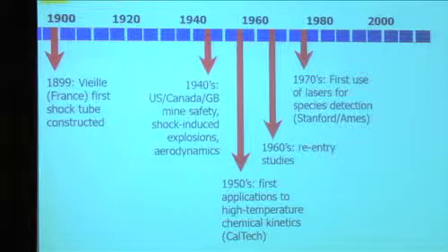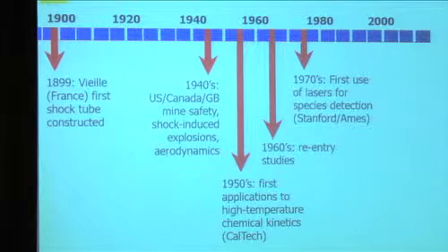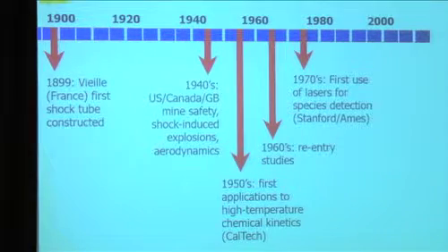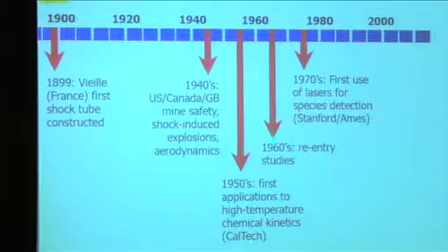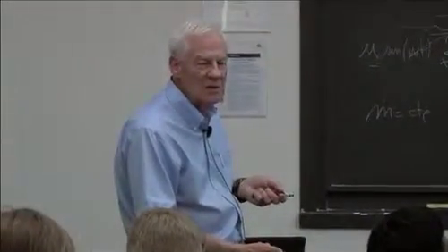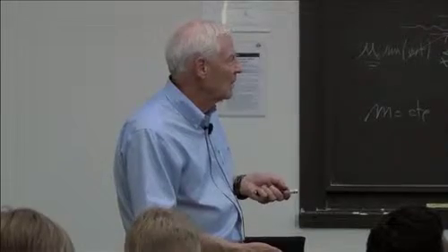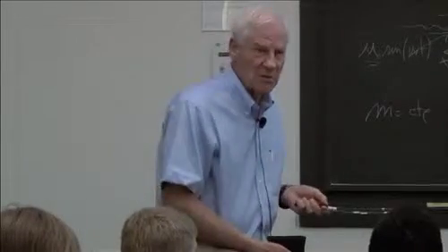And there are a lot of different designs. The shock tube design I'm talking about is called pressure-driven. It's the simplest, cheapest, safest. But I've been around shock tubes that are driven by electrical discharges that would rock the building when the discharge goes off. So they use different strategies. But combustion, the temperatures aren't that much, 1,500 degrees, 2,000 degrees. They were worried about 50,000 degrees or some extreme conditions.